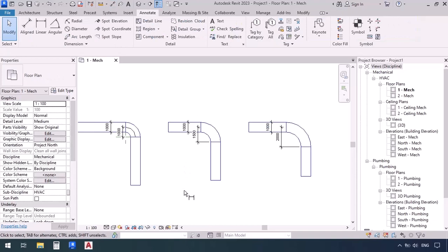We can do these measurements both in AutoCAD and Revit itself. So when it said that the radius of the elbow was 1W, 1.5W, or 2W, that actually indicated the size of the radius of the arc compared to the duct's width. So can we add a new radius? Yes, sure we can.